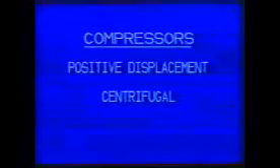This increase in the vapor pressure from compression allows the vapor to give up its heat as it passes through the condenser cooling medium. There are several ways to classify compressors. One is by the way they achieve compression. Another way is by the type of motor they have to drive them. We'll talk a little more about motors later on.